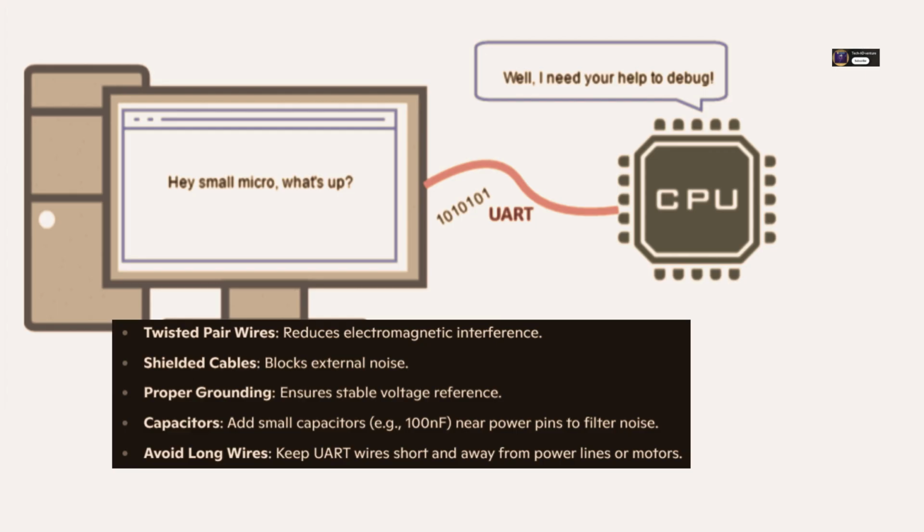Okay, lots of good techniques there. How would you typically test communication specifically between a PC and a microcontroller, step by step? Okay, testing PC to MCU UART. 1. Connect your USB to UART adapter to the PC's USB port. Make sure drivers are installed. Note the COM port number it gets assigned.